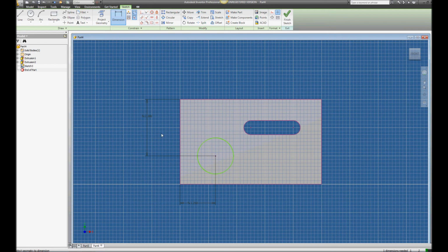Moved a little bit. Finally, we need to change our diameter. Of course, that doesn't look anything like the piece of paper. So we need to make this diameter. We are going to dimension diameter. Oh, look at that. We have our diameter feature already. We don't have to right-click radius. And we got to type in some sort of dimension here, telling us that our hole diameter is the same as the slot diameter.